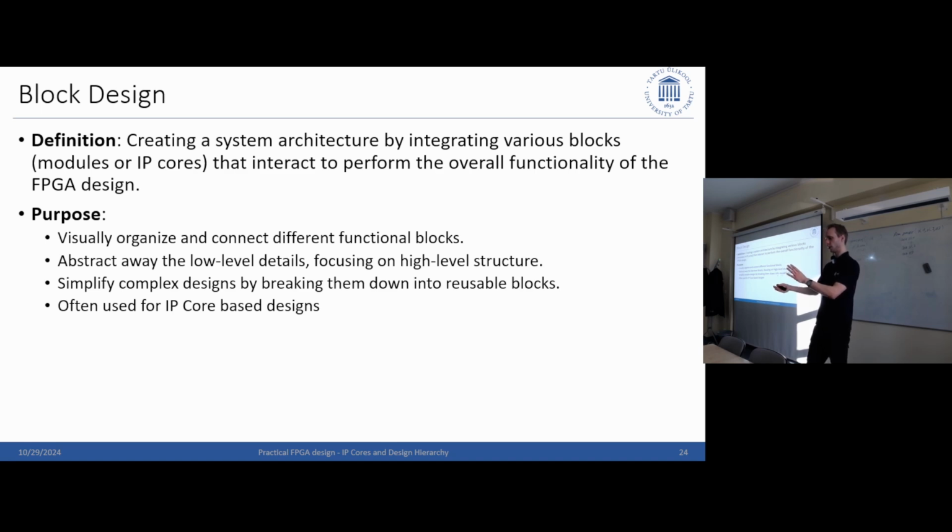Often when people integrate a memory into their design or provide an IP core for that, say I have a Samsung memory, some vendor might say, this is a radiation-hardened memory, I will provide a solution to integrate it into an FPGA. Then they will do this, but they also will emulate the memory, because otherwise you will never be able to simulate any kind of image or whatever you load in and out of the memory. And that's very, very common.